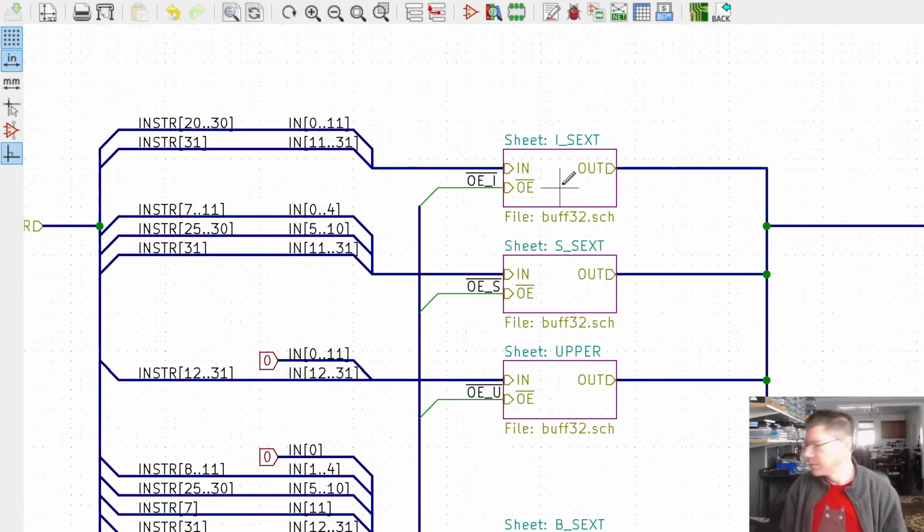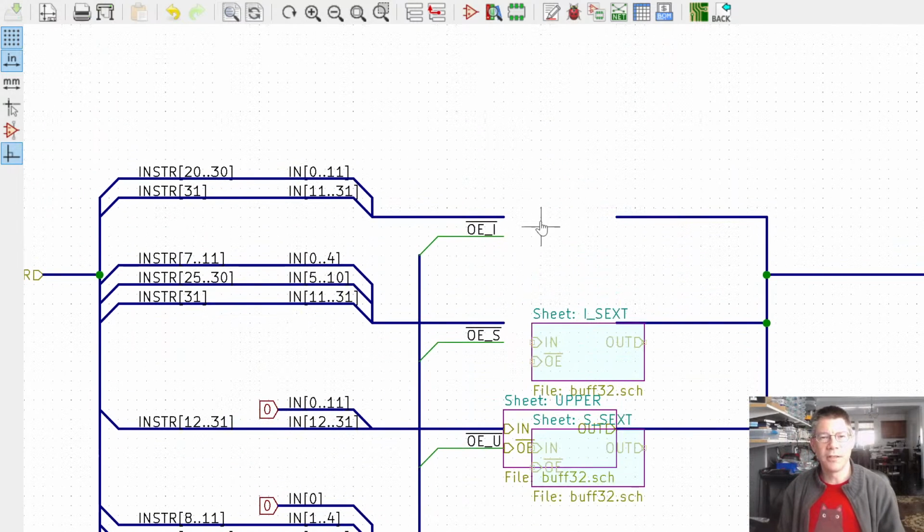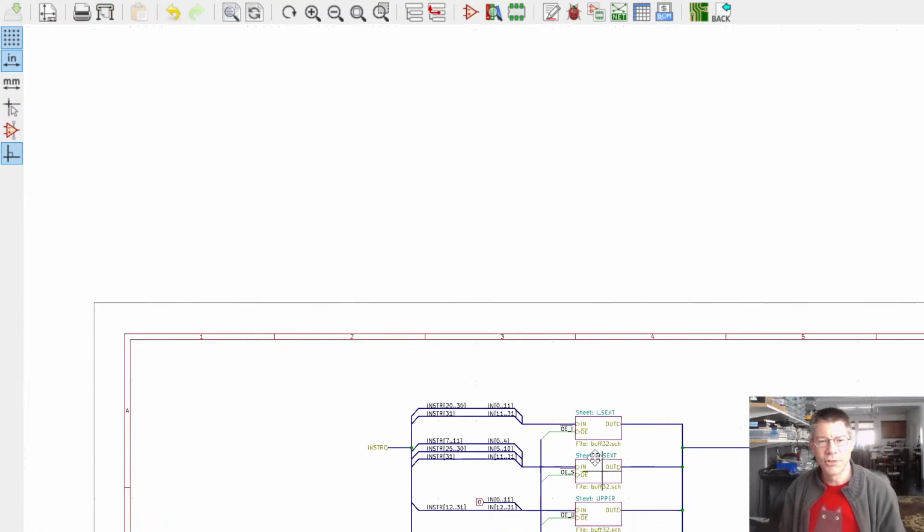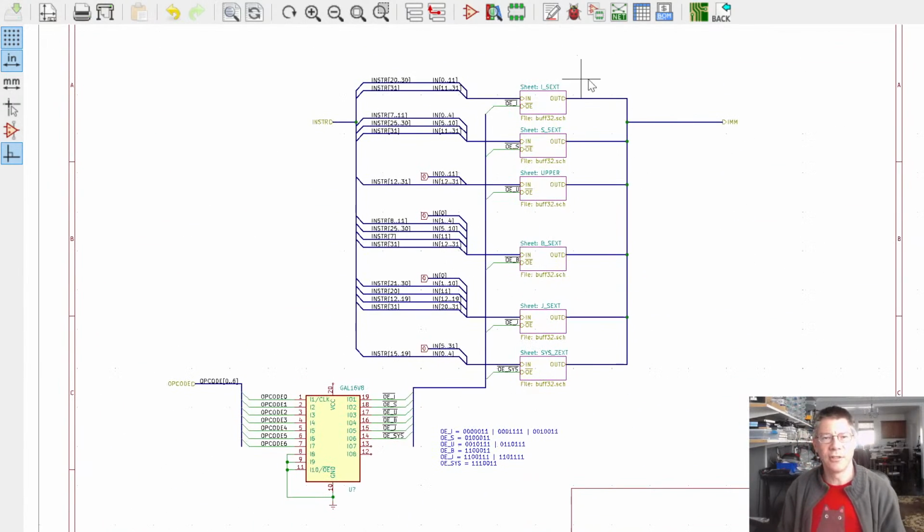Now each of these, we go into them. So what I'd like you to think of this section as is a multiplexer. The idea is that we are decoding the immediate value for all of the instructions, but we're only letting through the immediate value that is appropriate for the opcode. So that's why I have this, let's just call it a selector, and it selects one or zero of these 6 values, and then they all get tied together because it's a multiplexer.